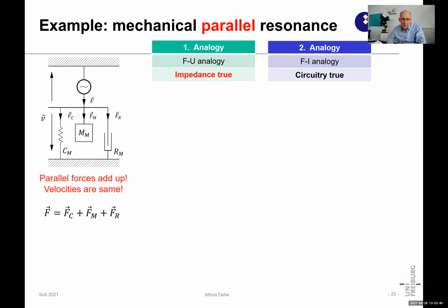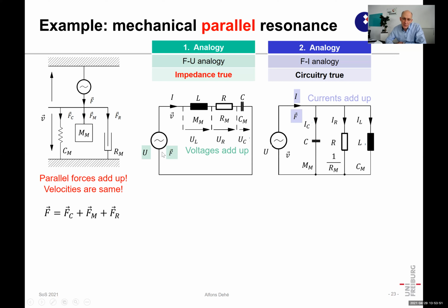Now, if you describe this in the first analogy, you simply say, I add up the forces, which is, in the analogy in my network, I add up the voltages. So this looks intuitive, therefore very often such circuits are simply described in this impedance, force-voltage analogy. Of course, you can describe it in the second analogy as well, but then you end up with parallel circuits. And the solution will be the same, just with a different implementation.